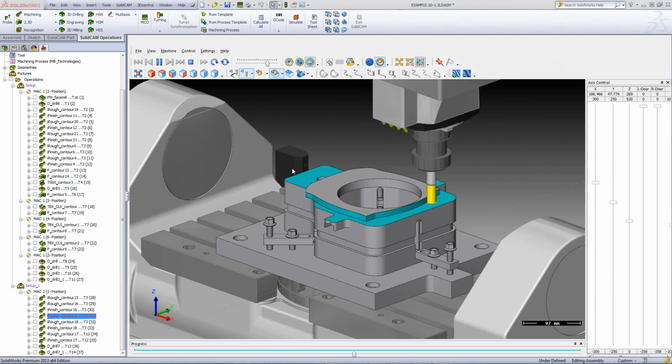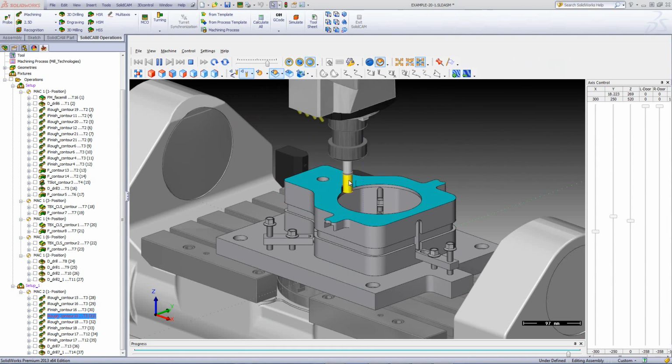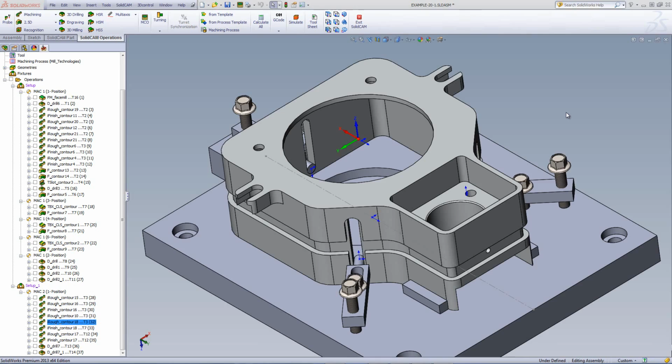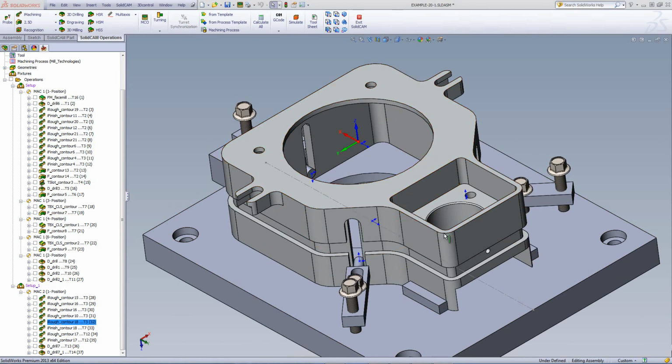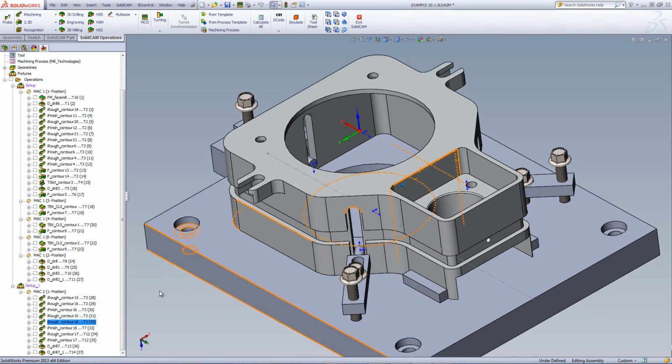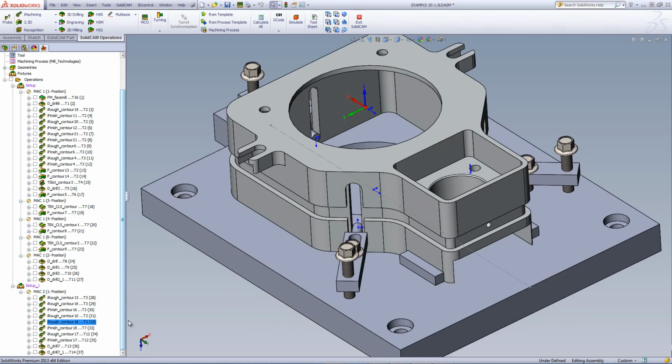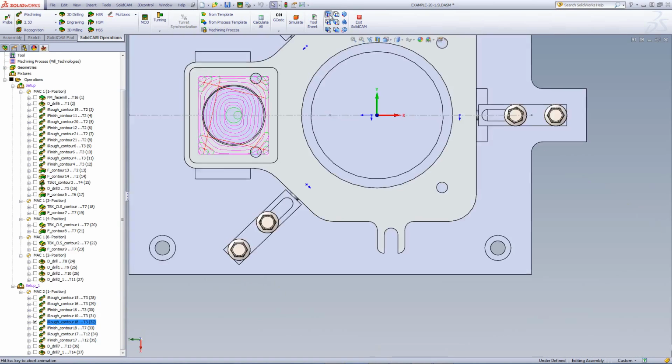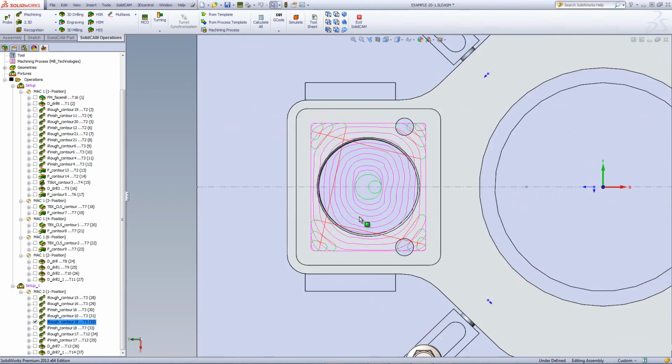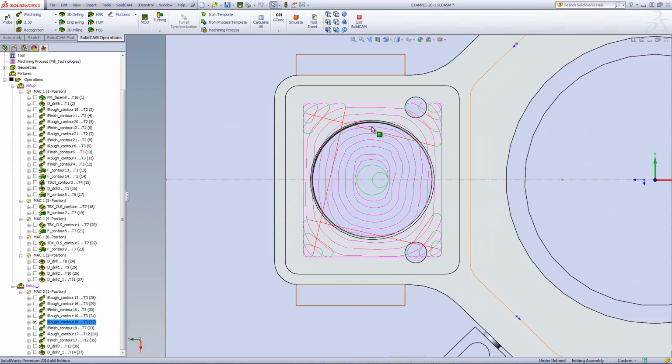And you can see that it works exactly around, cleaning up all of that material that was on that particular surface. Now, for my next operation, I still had to mill out this pocket over here. So again, just as before, I used the eye machining operation to mill out that pocket over there as well. Taking a look at the tool path from the top view, you can see that it has the morphed spiral tool path as well as trapezoidal for the corners itself.